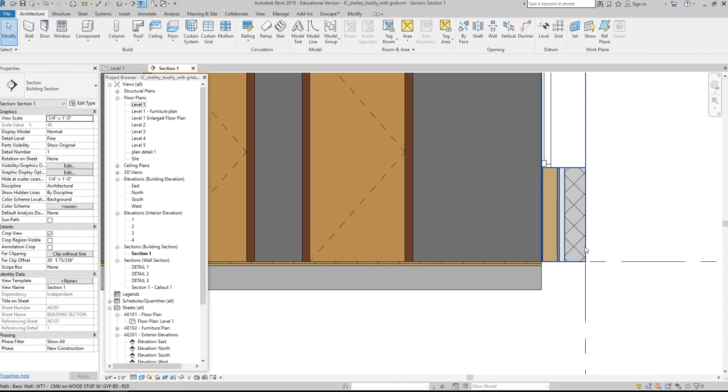But usually what happens is when we have our joists, depending on how you do it, because you can hanger them and do a lot of different things, you're going to have an exterior finish, whatever that ends up being, and then you're going to have your stud wall in here. We'll just cross-hatch that for now. And usually the floor comes in and rests on the foundation at a certain point, and then these stud walls come in and sit on top of that floor.